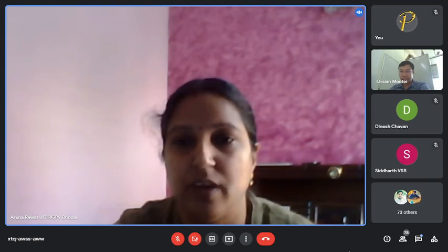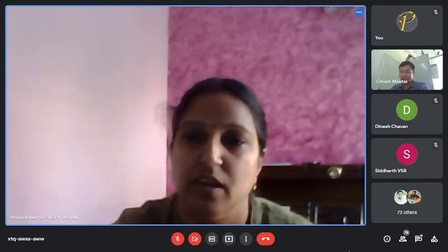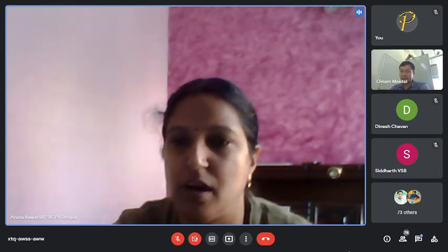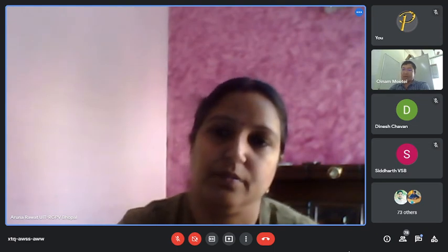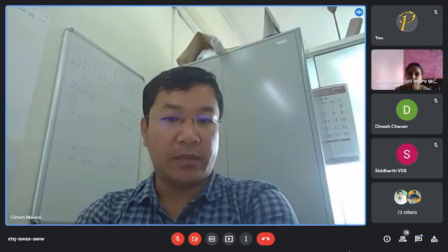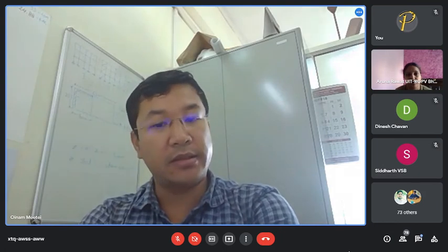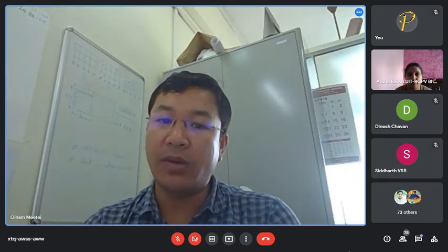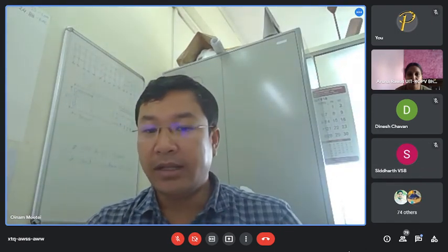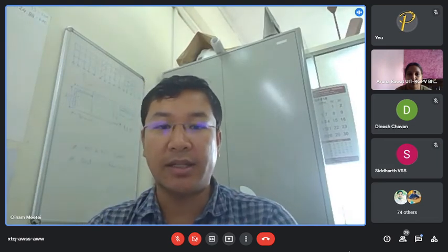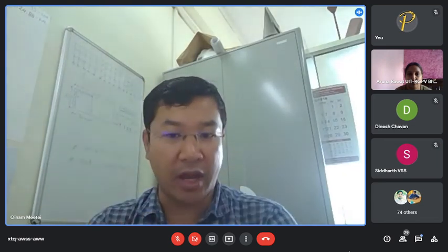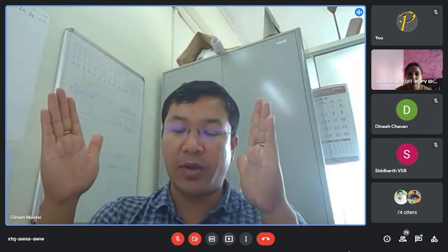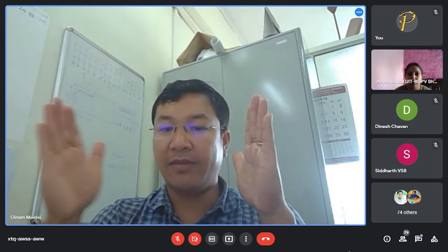Why does the Indian code have an R value for steel as 5 and for concrete 4.5, whereas in Japan the R value is 8? Actually, if you look at Japan, the R value is equal to 8, a particular value given as the response R value. R is nothing but, as I mentioned in my lecture, structural ductility. Structural ductility is your R value. It means if your R value is more, then from the yield point to the ultimate collapse point, the capacity is more. 8 means more, 5 means reduced.